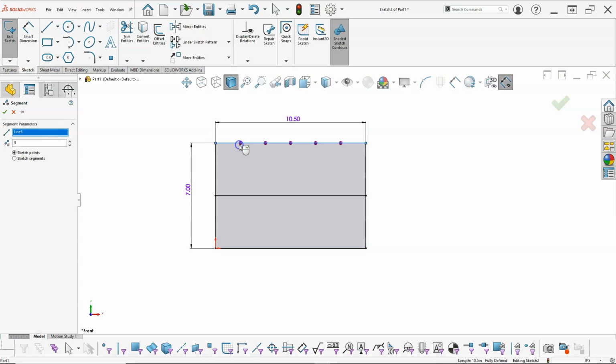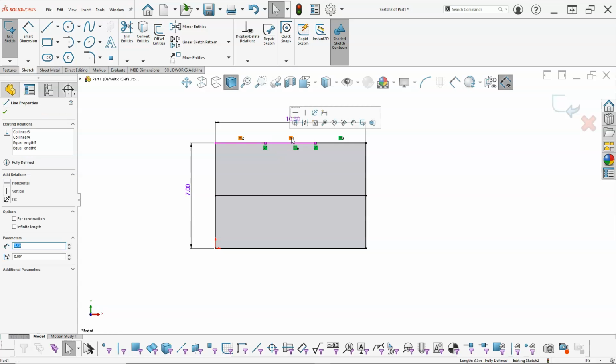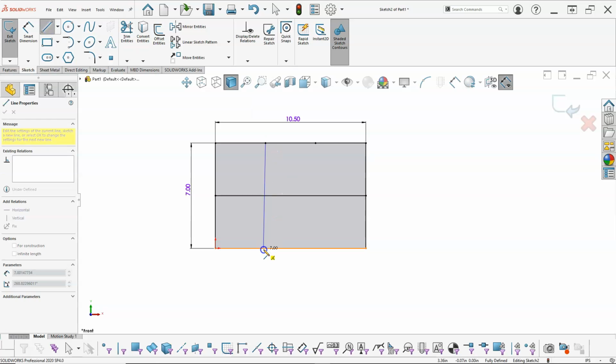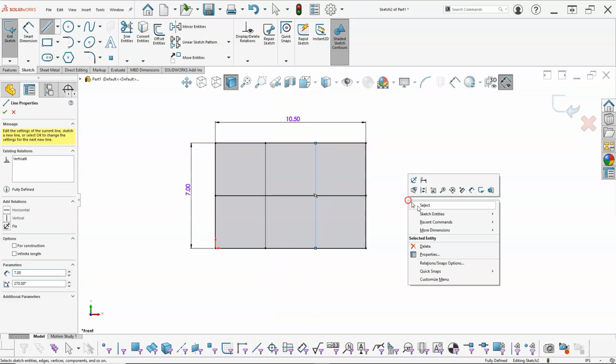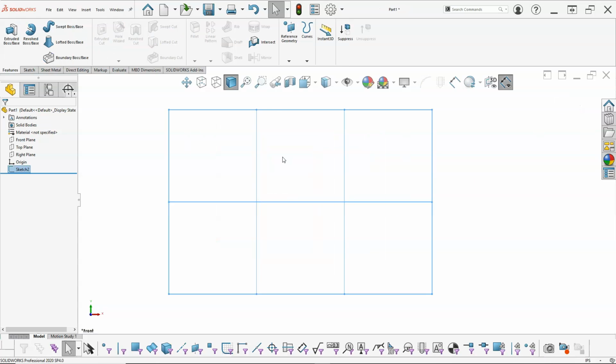and the segment parameters will be along that group. Do we want points or segments? So if I go to segments and tell it that I want 3 segments, we'll get 2 points along that line. And we have some equals, so I don't have to set those geometries to equal. I'll just pull the line away, and that gives me a layout for my additional sketches.